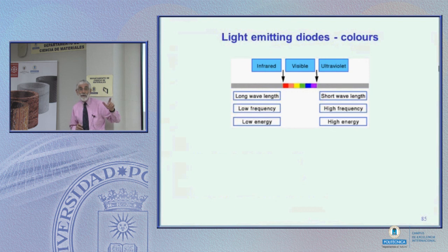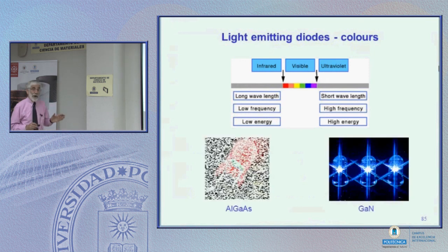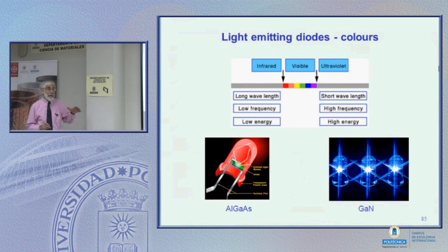Because the early ones, how many of you spent over the weekend time in a police station being questioned by your police? Just checking. You know those very white lights which they will shine on you? Maybe you don't. Good. But the point about this is that the early LEDs, because of the band gap and the energy, it is a very harsh white light. So what happens now is you have your LED and you put a phosphor behind it. So the light comes off, hits the phosphor, and that re-emits at a wavelength which is more warm and gives us a color that we like in our rooms. This is quite a white light, and we in general prefer to have a warmer, more yellowy light in our rooms. And now one can do this using a phosphor. So one of the problems was to get the right colors and to get the right wavelength from an LED to make it acceptable.